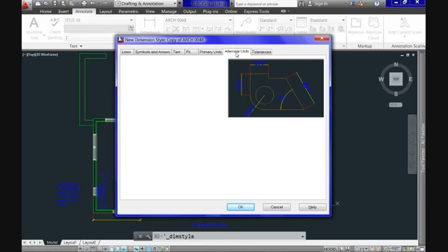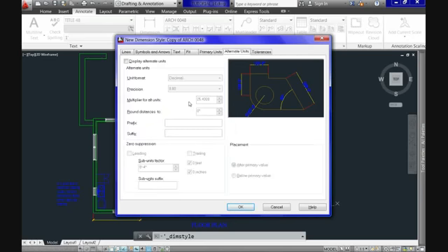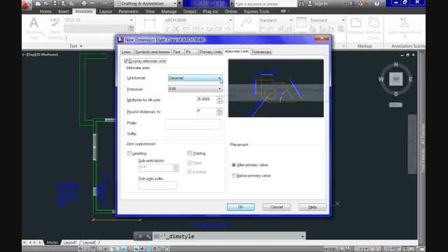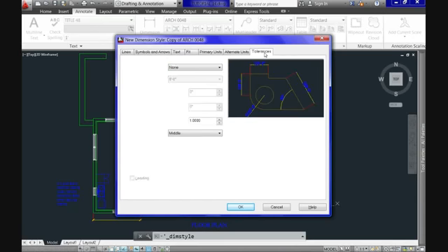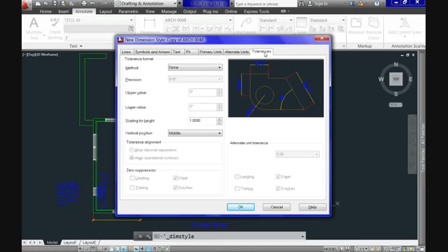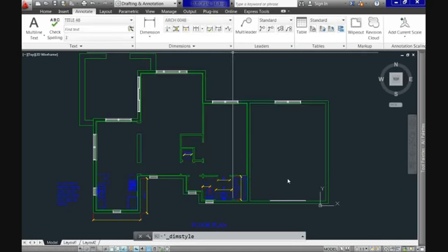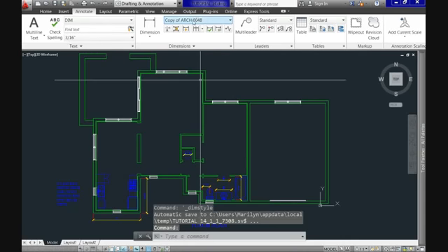On the following tab, we normally don't use it, but you can have values expressed with additional units of measurement, like for example, in both engineering and architectural, or in both inches and millimeters. Again, this is not common, as well as the tolerances in the last tab, which will depend on the specific discipline you are drawing for. Here you can select the method you prefer, etc. While visiting all of these tabs, you will notice that some options are not available, but once you're satisfied with your style, you can click OK, and it will be the current style in the annotation tab of the ribbon.